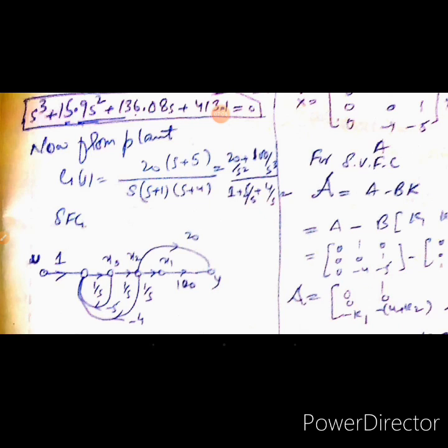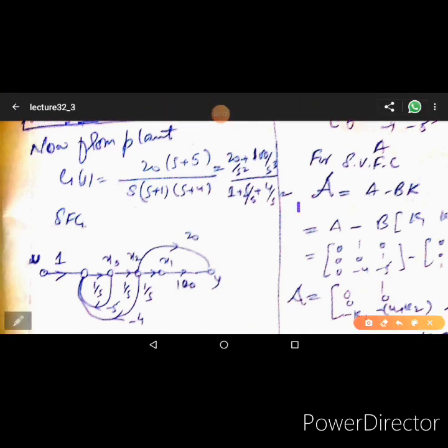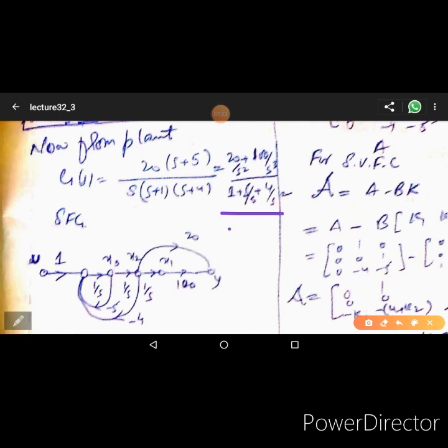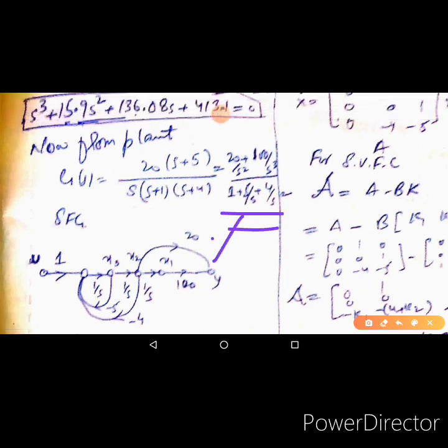And once we have the state variable model of the plant, then we will use the usual method that we have used for the state variable model and state variable feedback, which is covered over here next. So first of all, we make the simulation diagram. For the simulation diagram, we multiply and divide by s cube and we get this form of the transfer function. And then from this, we make the simulation diagram. We connect three integrators in series, which you can see over here.